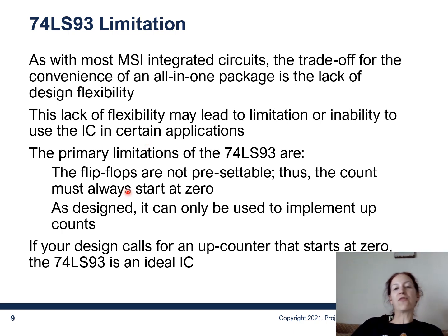So for example, the flip-flops are not presettable, thus the count must always start at 0. So in the last activity, I had you modify a circuit so that it started at 1. If you were using this particular chip, you wouldn't be able to do that. And then as designed, it can only be used to implement up counts. So if you need a down counter or you need some kind of counter that can be modified to go from up to down, you wouldn't be able to use this IC. But if your design calls for an up counter that starts at 0, this is ideal.